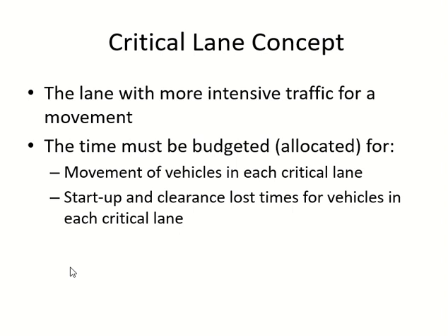And what if you have lanes which are in different directions? We are dealing with all lanes which are going in the same direction, but you may have a lane which is for straight and left both. Then for sure it will not be the same. You may have one lane which is only for the left, and then 2 lanes which are for straight. For the straight lanes the flow may divide almost equally, even if it is not exactly equal. If it is near to 50%, we can assume, okay, fine. But what about the left turning? It will not be the same as the straight.